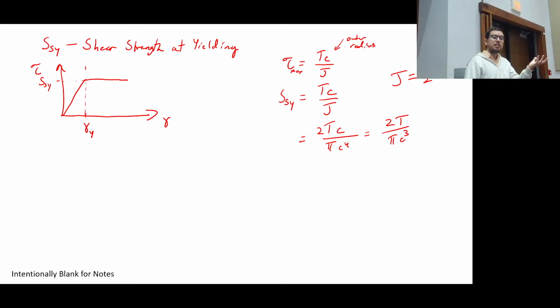And it says something important, that if I want to decrease the amount of shear stress that my selected material is experiencing, I have two options. One is to design my system to have less torque. Maybe I choose my ratio of teeth on my sprockets so that I only get to a certain amount of anticipated torque, right?